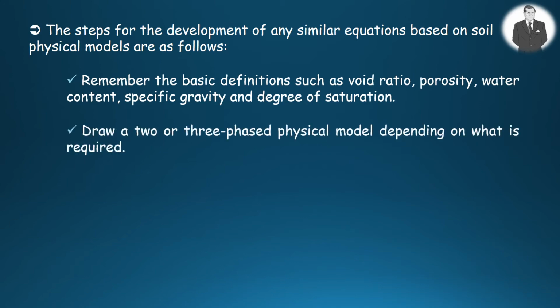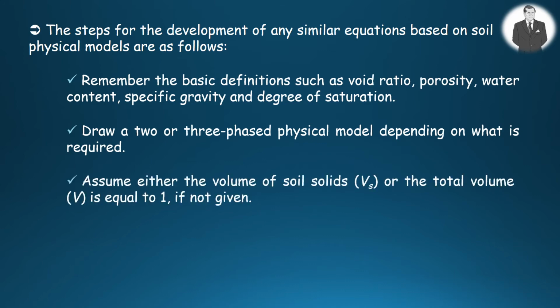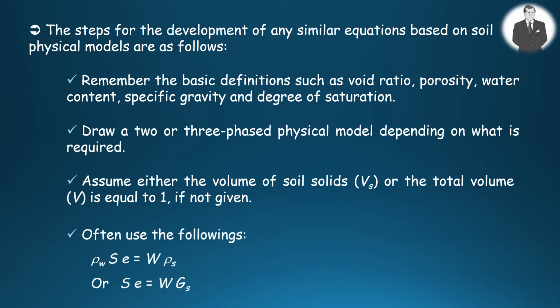Draw a 2 or 3-phase physical model based on what is needed. Assume either the volume of solids or the total volume is equal to unity if not given. And usually make use of the expressions given here.